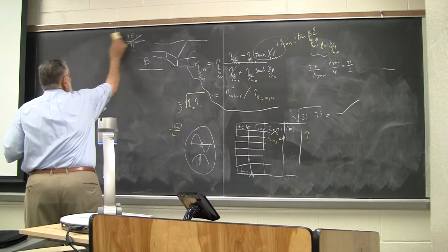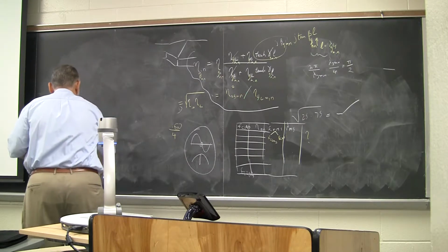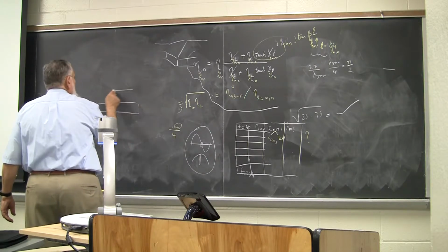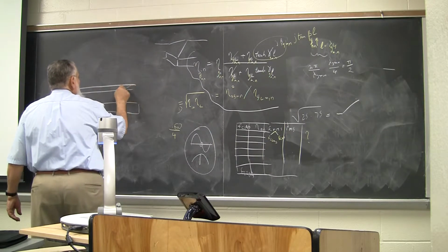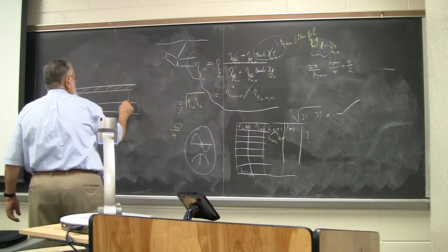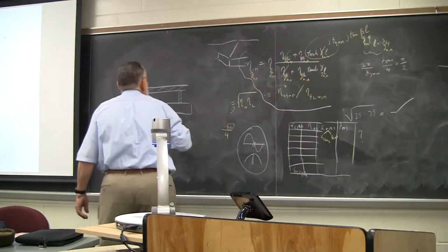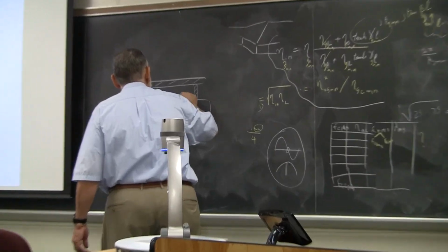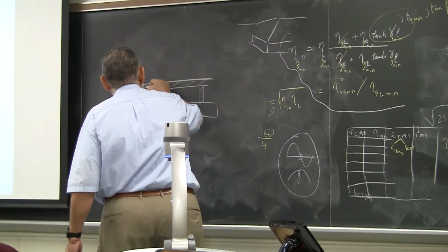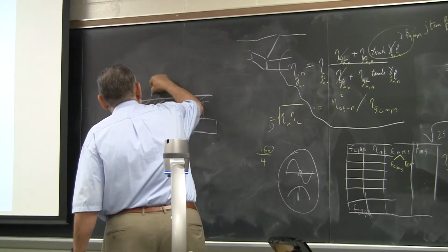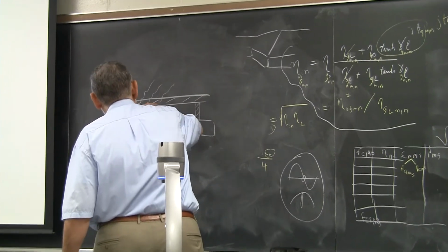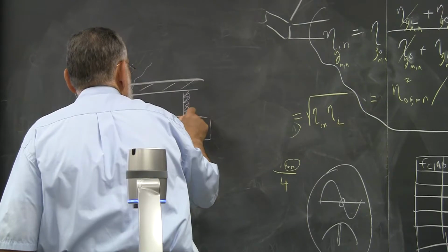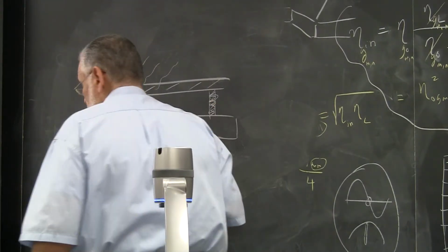First of all, if you imagine that you have a ground plane here, and another layer here that you want to make ground, and eventually you're going to connect them with that, all right? Obviously, you know that there is some resistance everywhere in there. These are not perfect conductors, and these vias are basically resistive as well as inductive.